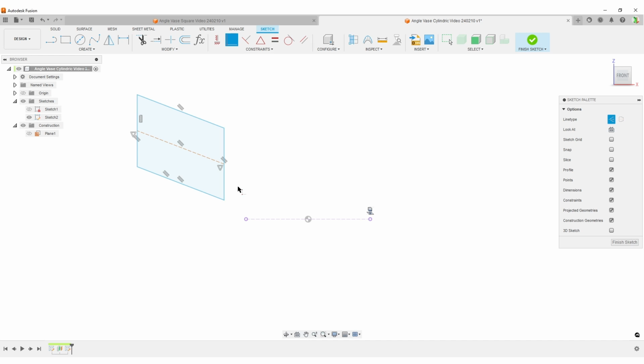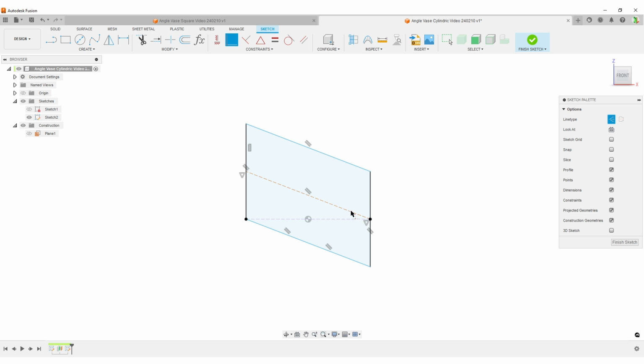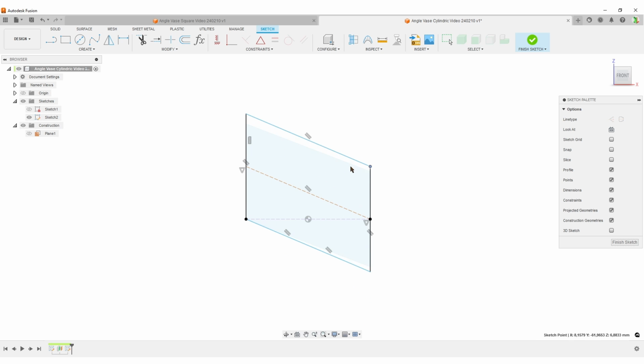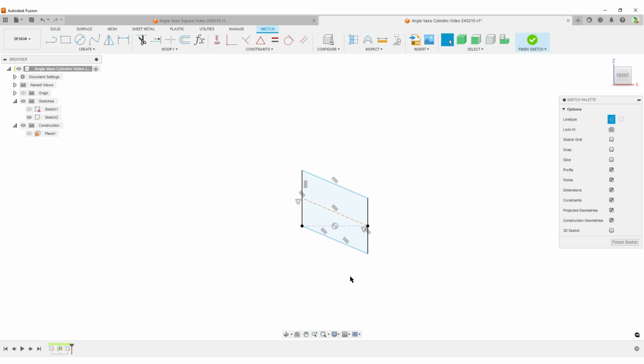We're going to add a constraint to the mid of it. That's here, over here, and this point over here. So we're starting to get some constraints, like definition of lines. These are now defined in width in this direction. What we have not decided is the height of this part. So this height is later going to be used in a rectangular pattern to spread this part up and down in this direction. So we can use this to drive our design slightly.